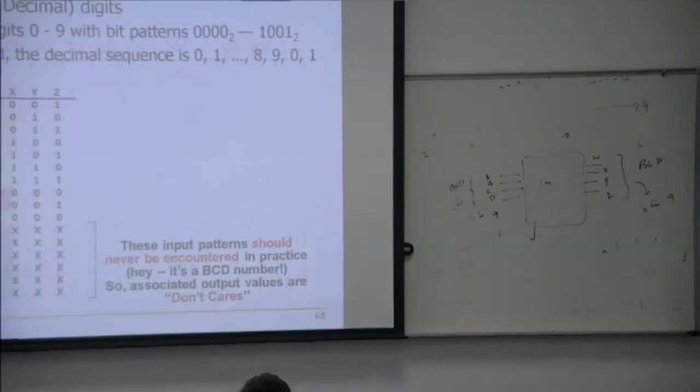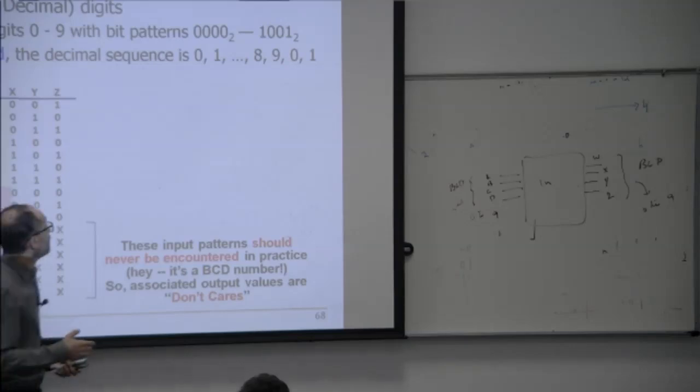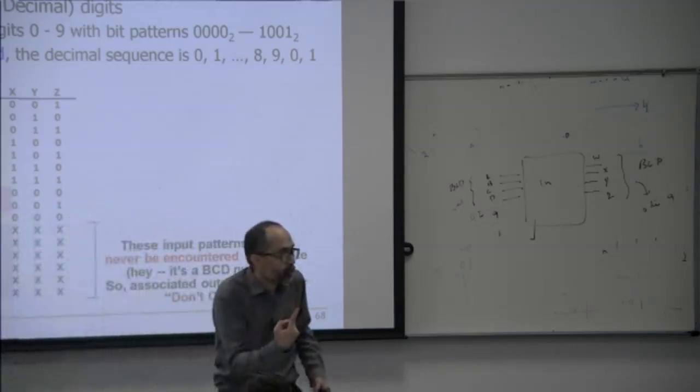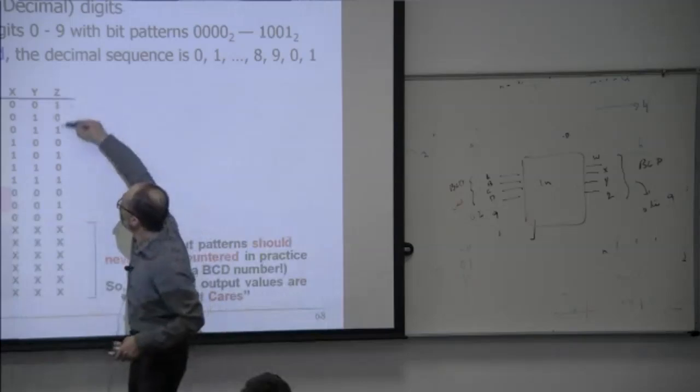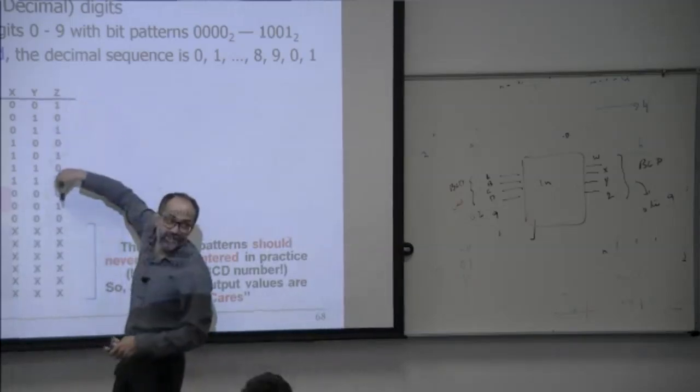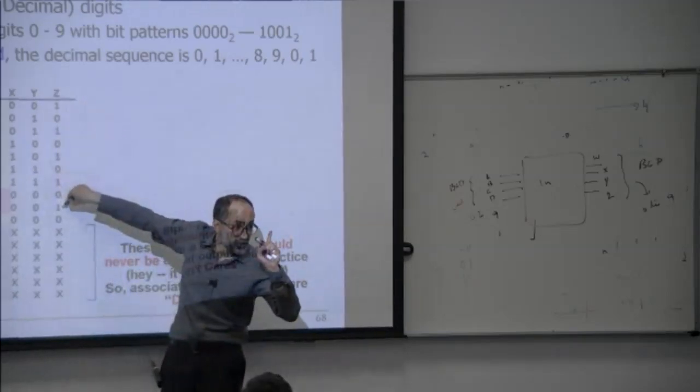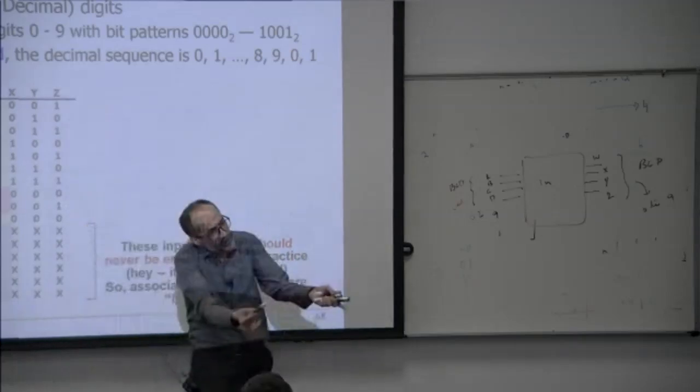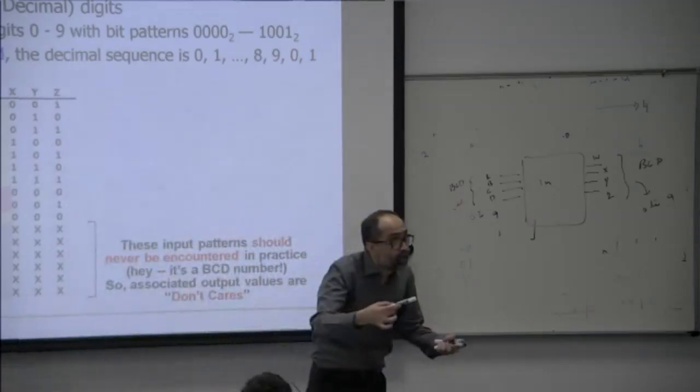Yes, please. A1001, why don't we make it also don't care? No, but the output is weak. Okay, we can also define another signal, overflow. So we can have another signal, overflow. For all these cases, for the 8 combinations, overflow will be 0. And for this case, 1. So we can also do that. Up to you.